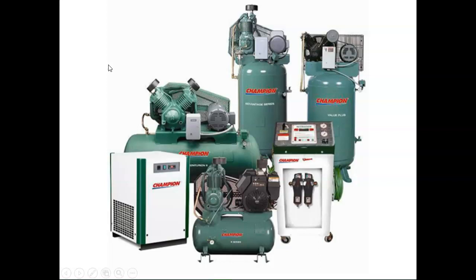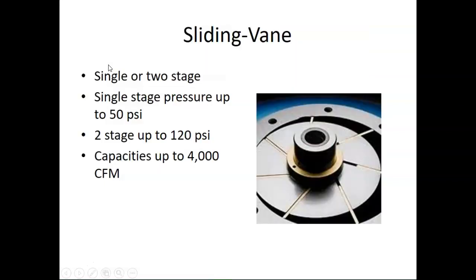But one of the things you might want to consider when you're getting any of this is how are you going to drain it? Because you need to drain it periodically. I would say at least once a year. You need to make sure you pull all that nasty stuff that's in there out. Probably want to do it maybe once a month, or you might have an automatic drain elsewhere in your system to pull all that water out of there.